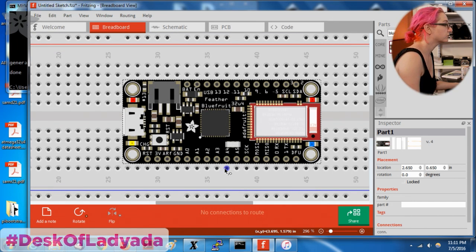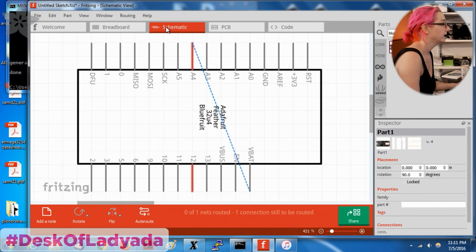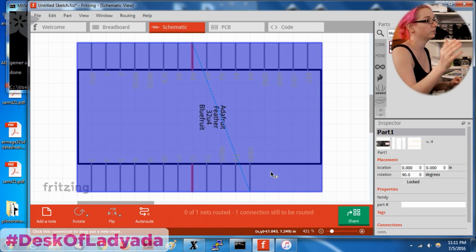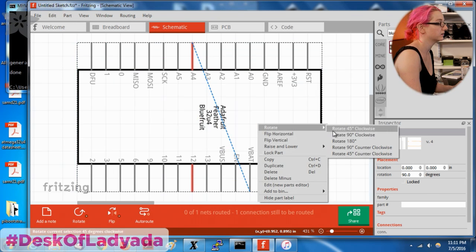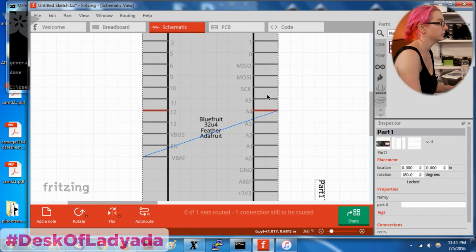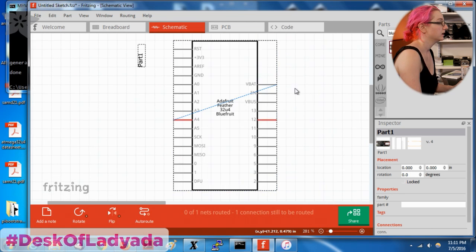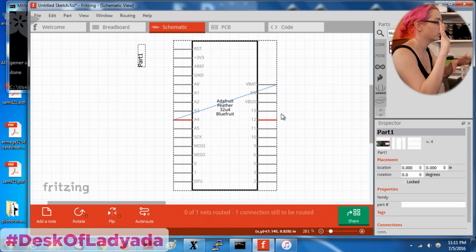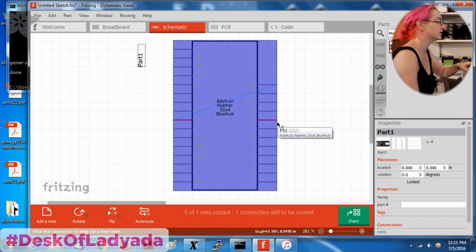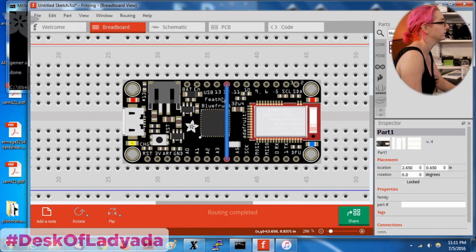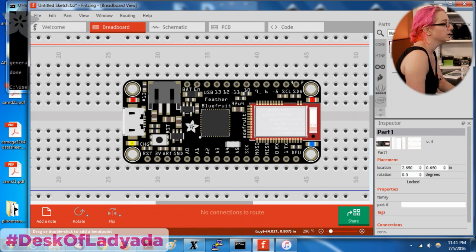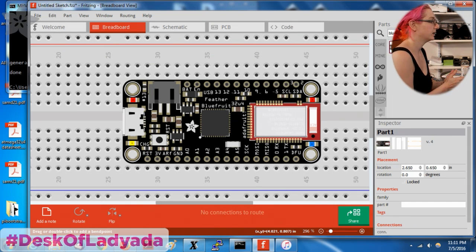One thing that's true is if you try to connect A4 to 12 and you look in the schematic, it's actually going to VBAT, because remember we moved the schematic pins down just a little bit. Hold on, rotate 180. It gets confused. The pin was up here and now you moved it down here, and it doesn't like it. So you just have to do a little bit of cleanup. You open up the part editor.